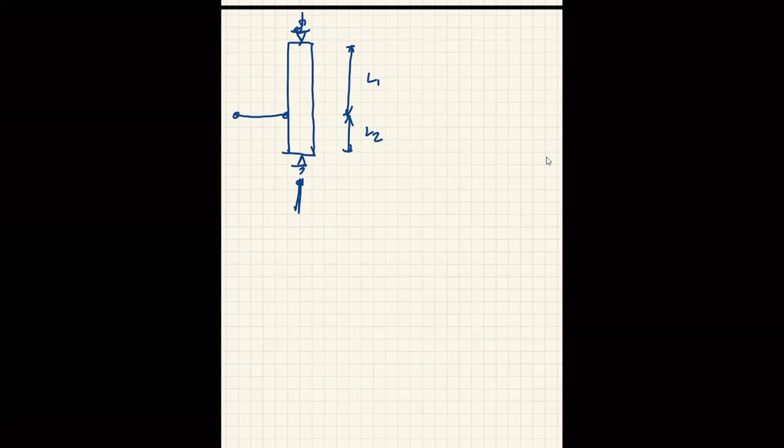On the other hand, if we change the brace to the upper one, that means the lower part will become the longer, right? If I move this up, this is where the lateral movement is prevented. That's the point of the bracing: you prevent lateral movement. Anything that prevents lateral movement becomes a brace point of your structure. Crystal clear? Yeah, clear.